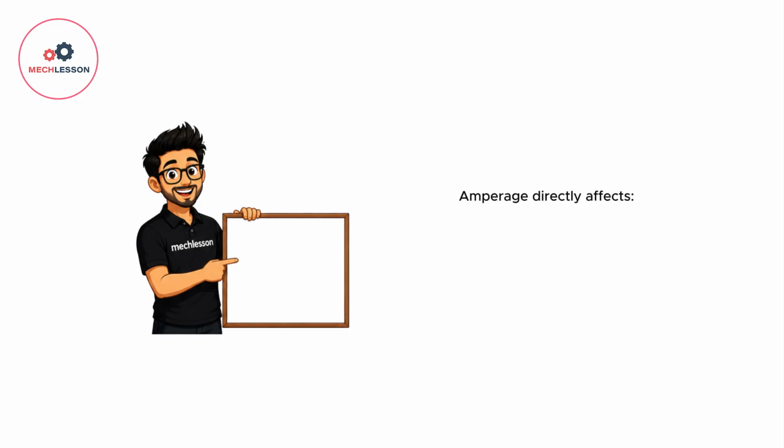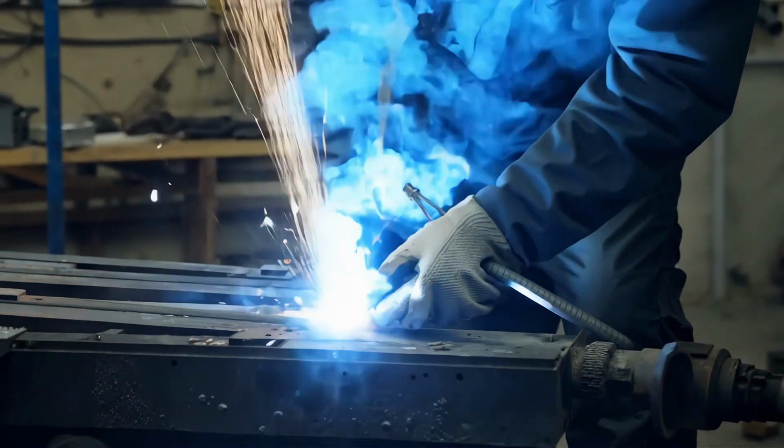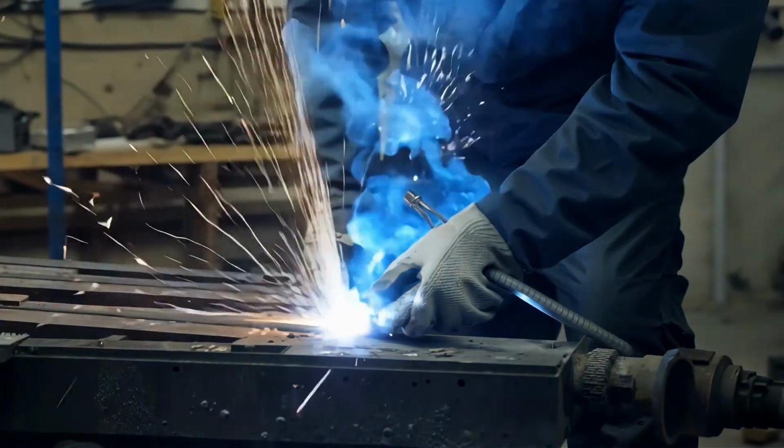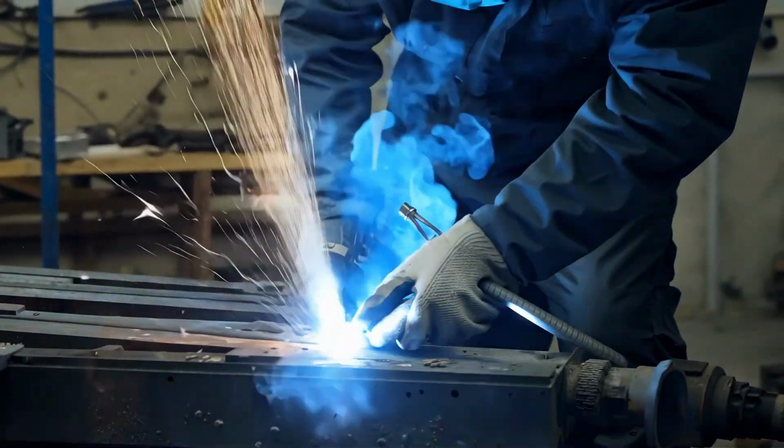Amperage directly affects penetration, weld size, travel speed, and weld quality. Too little amperage may result in weak welds. Too much can burn through the material. Learning to control amperage is one of the foundations of welding success.